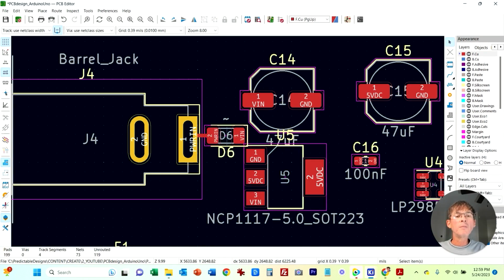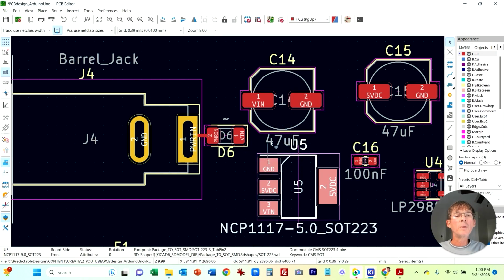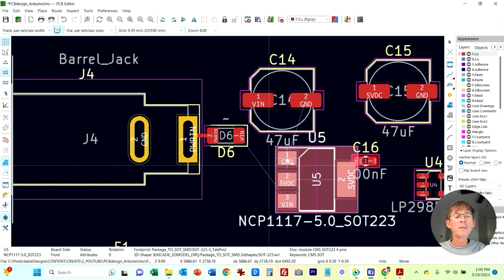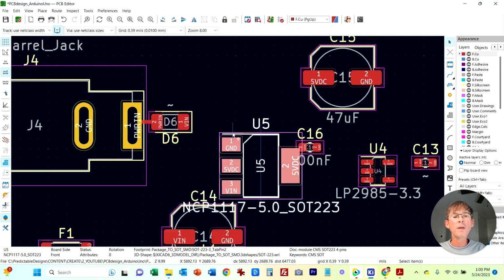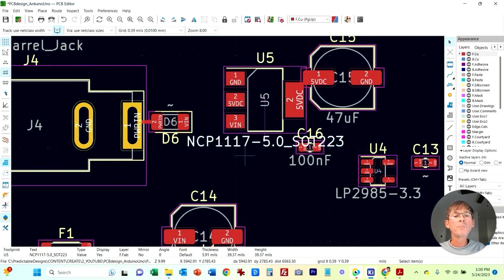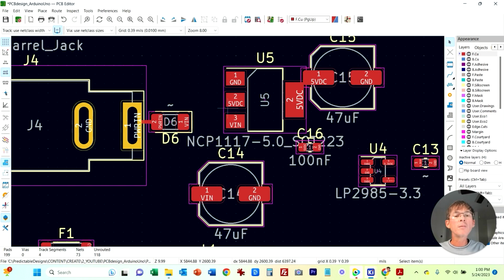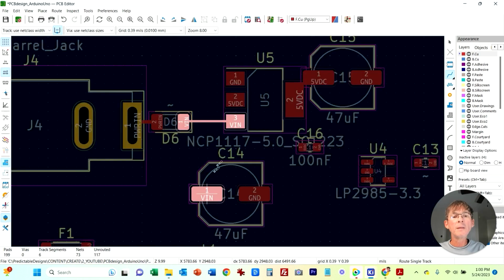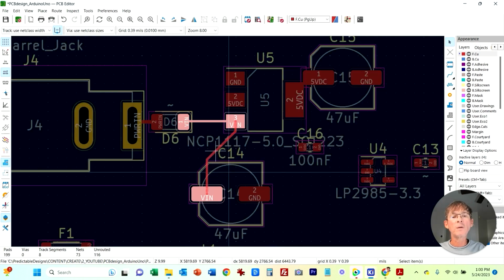Okay, then the VN comes through that diode, and now let's see. It's going to do 2 things. It's got to go mainly to the regulator, but then we also are going to have this capacitor here. So let's go ahead. I'm going to move this right here, and I want to put this close to the pad. So I'm going to go from like that, and then connect that there because we want it ideally on the pin that it's connected to for the regulator.